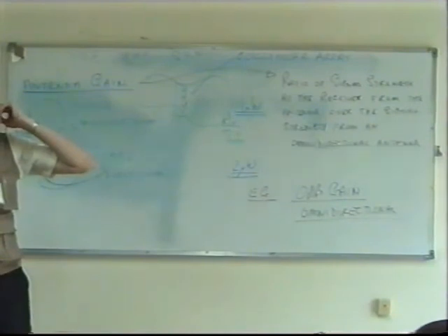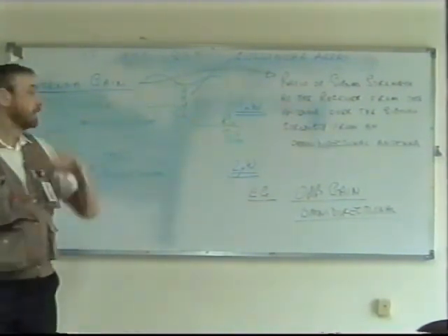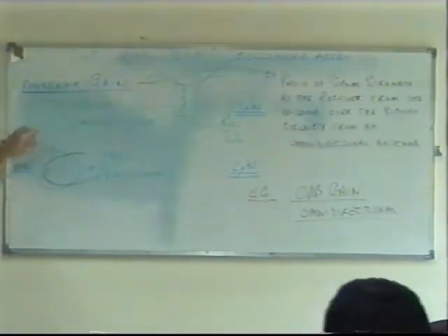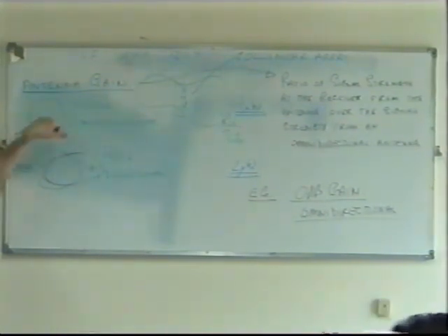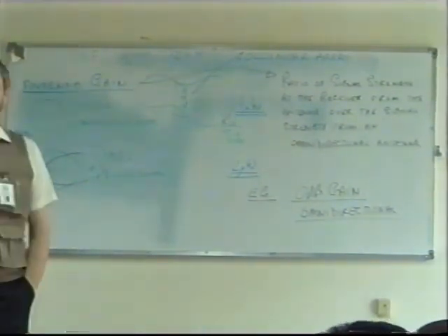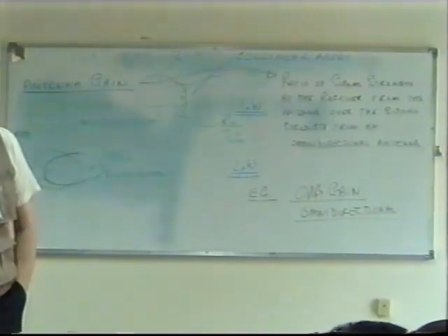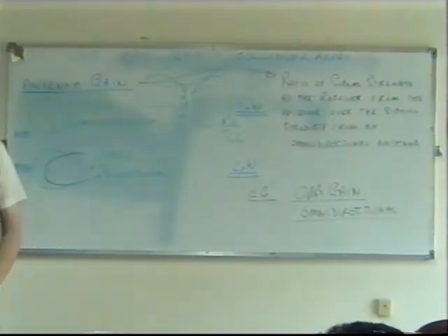Above the level of the noise. If you use a 100 watt transmitter with an omnidirectional antenna, it's the same as using a 50 watt transmitter with an antenna of 3 decibels, because effectively you're doubling the power.